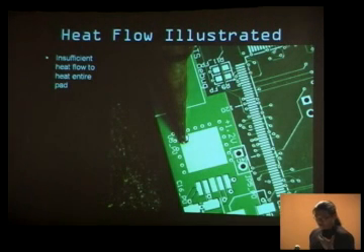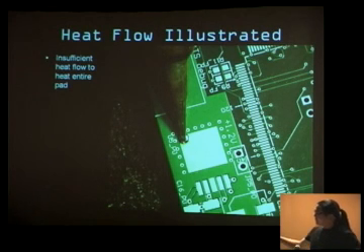So I just want to really drive this point in because I see a lot of people starting with soldering and they get really frustrated. Here is a pad on the circuit board. It's a pretty big pad. And you can see these little vias here. Those are all going to the ground plane. We need a huge sheet of copper, right? This soldering iron is not big enough to heat it up. In fact, in the corner here, I'm trying to pull heat into it. And you can see that this whole region here still looks dull.